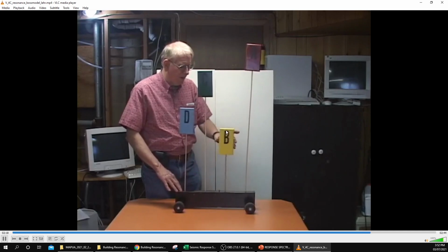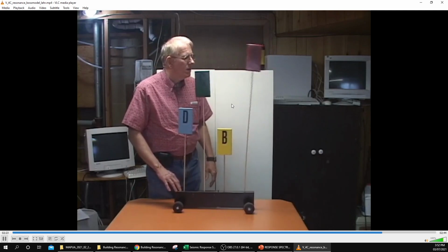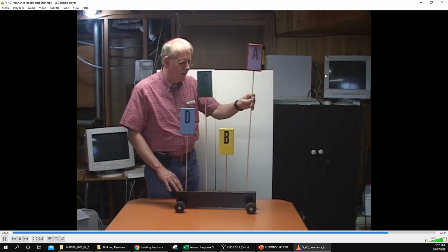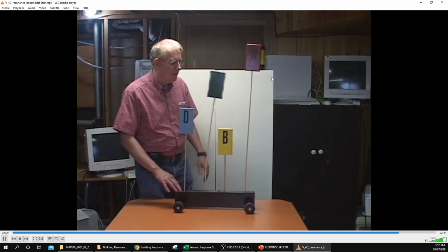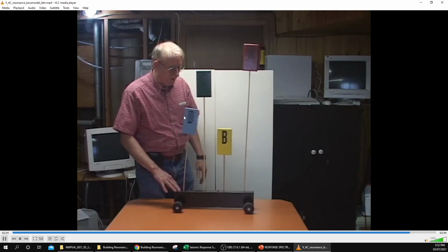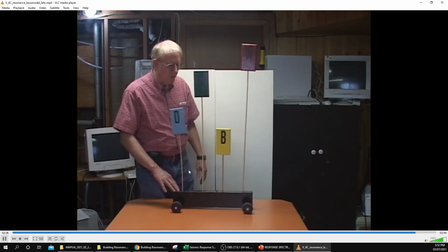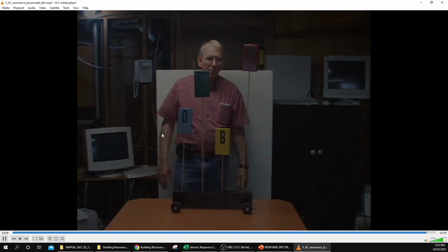So you're seeing a high frequency shaking. And if I go to very slow, low frequency shaking, the taller building moves most. And you can also go to intermediate frequencies, an intermediate frequency shaking for this one, and a slightly smaller frequency shaking for the blue. Right, so I hope that explains to you how resonance works.